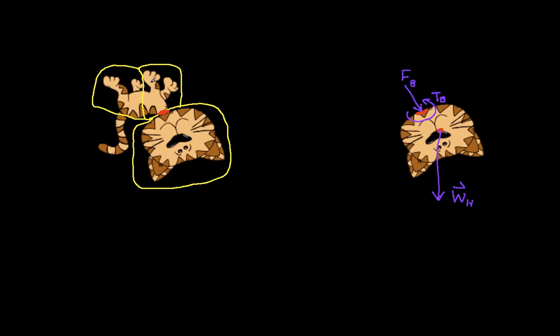One last thing to notice, when we're talking about how connections are represented between the environment, we typically draw forces and moments on the edge of the free body diagram. When we're talking about things like gravity, we draw the force or moment internally to the diagram, from the center of gravity in the case of gravity.